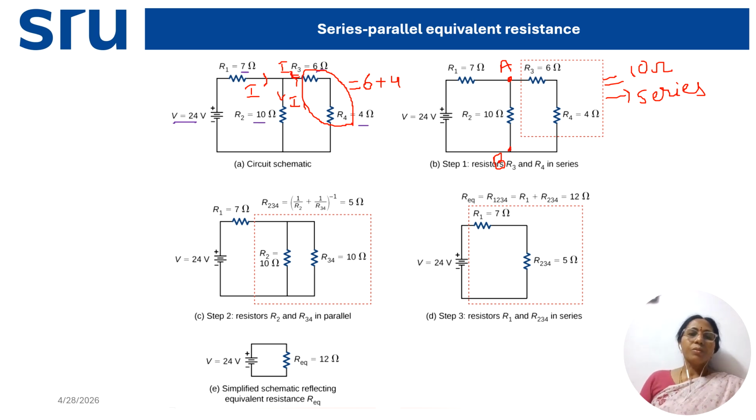Okay. So now 24, as it is 24, after that a 7 ohm is there, but here I have a 10 ohm resistance between A and B. Let us draw the 10 ohm as it is, but together 6 and 4 become 10, so another 10 ohm also comes in between the A and B terminals. So after this, this is the reduced network.